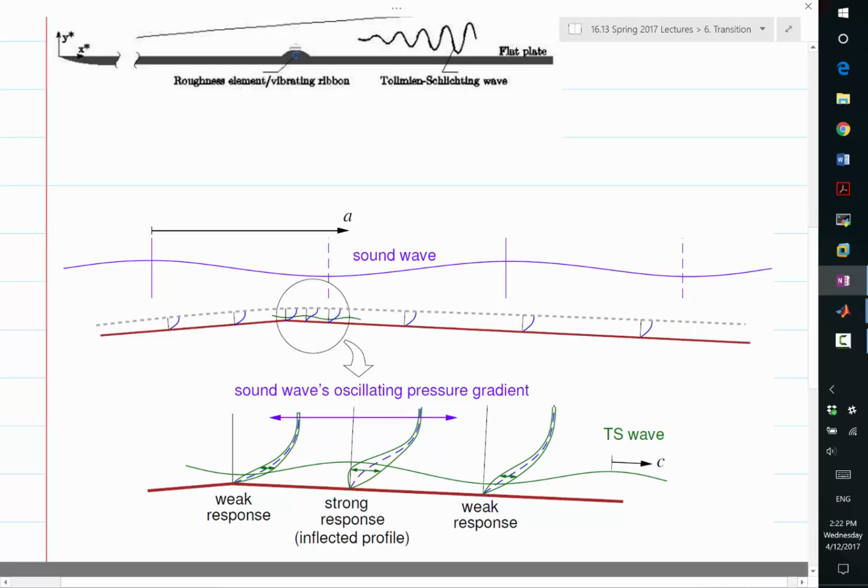If you have a bigger H, it responds more to any pressure gradient, compared to a lower H. Higher H has a larger portion where you have slow velocity, and slow velocity responds to pressure gradients a lot more, because you have U partial U partial x equal to minus partial P partial x.